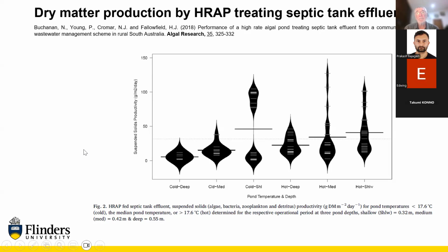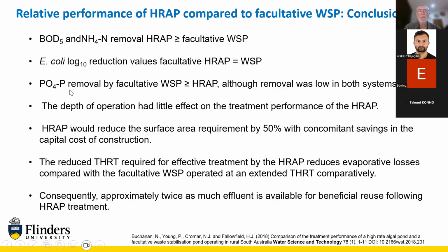Yes, sure. An exciting question, or maybe not. So when we got to the end of this, I've only shown you the comparison with the facultative pond and not the maturation pond. In actual fact, what we showed was the benefit of using a high rate pond. The big difference was retention time: only 5 days in the high rate pond, 30 days in the waste sterilization pond. We had the same degree of treatment with a much, much smaller pond for the equivalent volume treated.